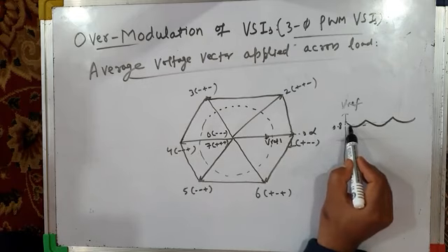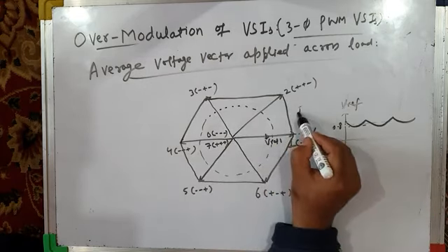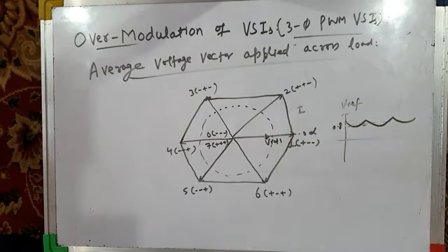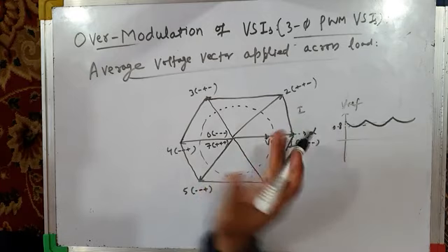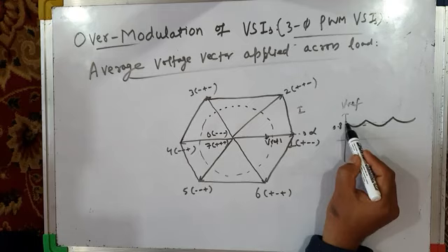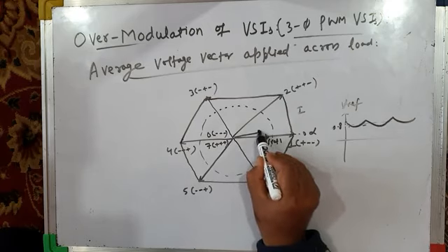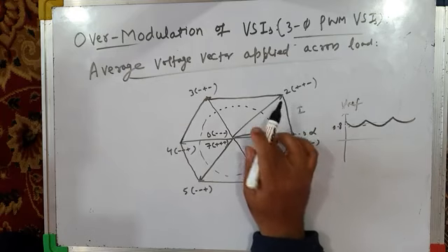Then as it rotates, this is your sector 1. By time averaging of these vectors, two active vectors and a null vector, you produce a rotating reference vector. As you take more and more samples and time average these three vectors, for the next sample you can see its magnitude now reduces. It has less magnitude. So for the next sample, it's somewhere here. It's less than this, so it's somewhere here.